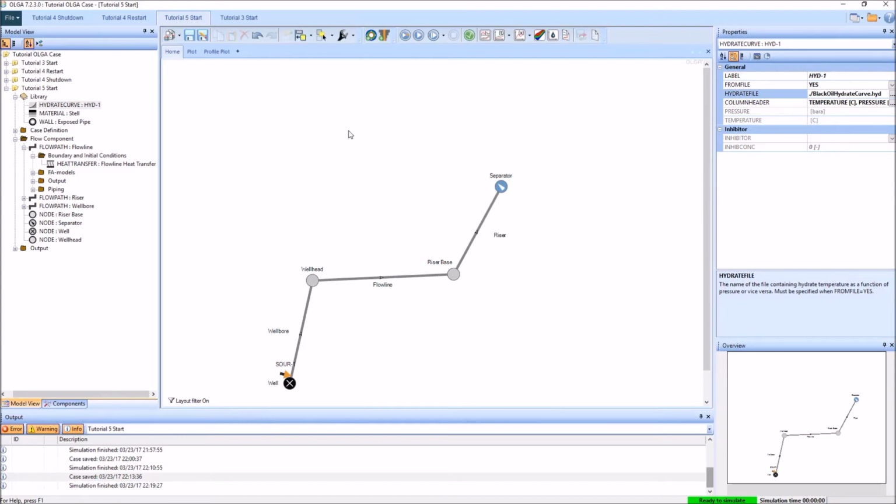So what they aim to do is to prevent hydrate formation over the residence time of fluid in the pipeline. So what that means is that if you have some oil coming from the inlet of your pipeline, by the time hydrate has begun to nucleate, it's already exited the pipeline, and so therefore hydrate formation within the pipeline itself is not a problem.